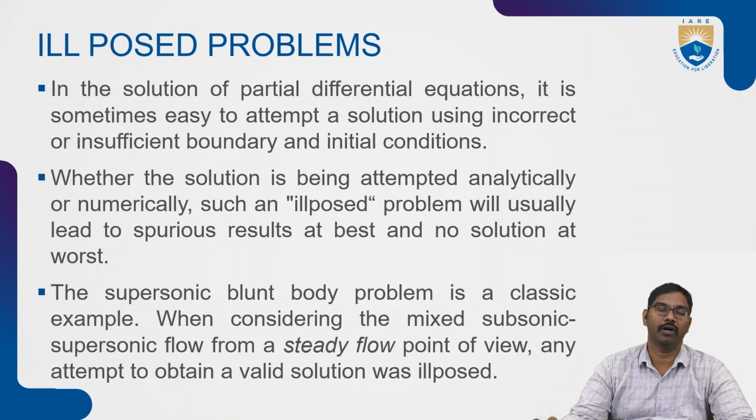This is caused by inaccurate or insufficient boundary conditions or initial conditions, or maybe the mesh which has been defined, or the material properties which we have defined. There may be so many causes which define the problem setup as an ill-posed problem.